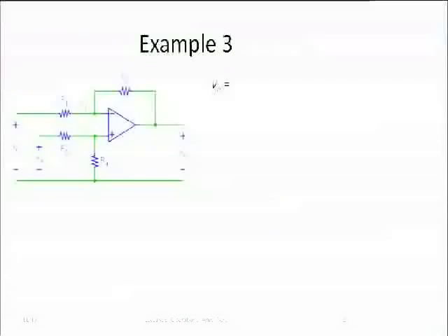So we can also do subtraction. A little bit more complicated circuit here. Again, what's the first thing we have to do? Feedback. Is it negative? Yes. Okay, then, because we have negative feedback, we can say the voltage here is 0 volts, right? So then I conveniently already labeled these. So Vi1 is equal to Vi2, right?